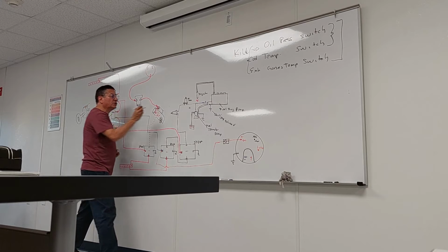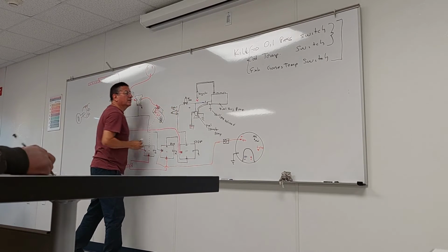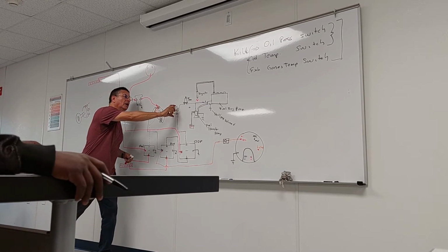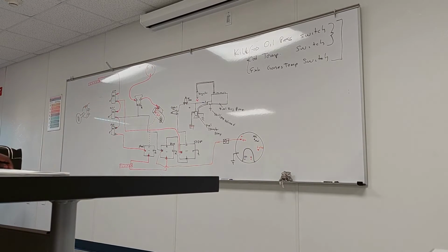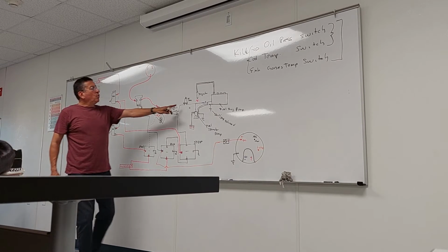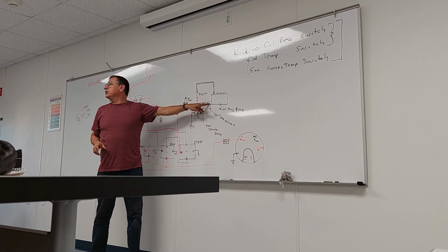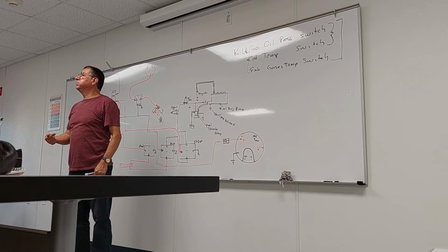And the coolant temperature switch is located here. If the temperature passes the limit or decreases below the limit, it opens and interrupts, and kills the engine. When the switch goes off, the fuel injection pump sends a signal to the computer to shut off the engine. Pay attention. When this one is open, the solenoid no longer receives the signal and closes, and no more fuel enters the engine.